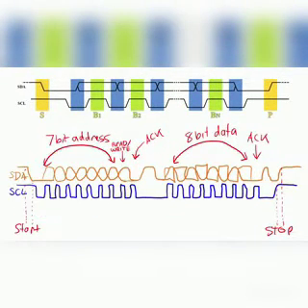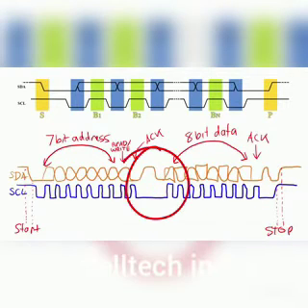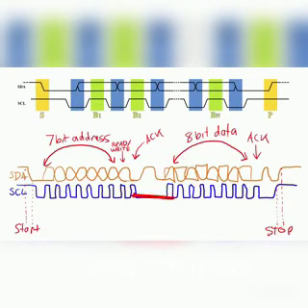Between blocks of data, for example, between the address and the data blocks, the clock line is held low, but the data line is allowed to go high. If you were bit banging this, for example, this makes things quite simple because your function that writes data only needs to clock out 8 bits of data and before and after the transaction have a start and stop condition.